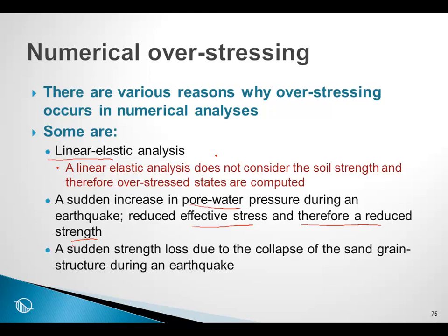So in some cases, yes, overstressing is purely numerical by the type of constitutive relationship we have chosen, but there are field cases where there may be a reduced strength, and by having an analysis type in SIGMA/W, such as the stress redistribution analysis type, we can look at field cases where there has been a true strength loss for whatever reason, and look at the associated deformations related to the strength loss.